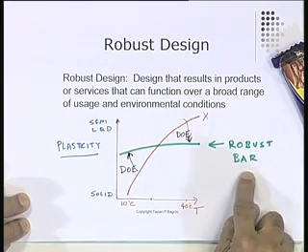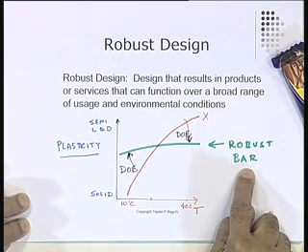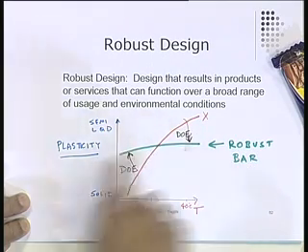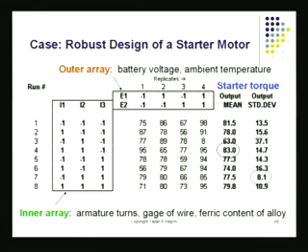When I'm trying to design a robust chocolate bar, I'm trying to seek that design which has the smallest amount of S squared. And this is exactly what we'll be looking for when we look at our matrix here. We'll try and find the setting which gives me the smallest variation. As far as strength is concerned, this is the setting 1, 1, minus 1 for I1, I2, and I3. This is going to give me the strongest signal, that is the maximum output mean. But as far as robustness is concerned, it's going to be this setting there, minus 1, 1, 1. So this is going to be low, high, high.